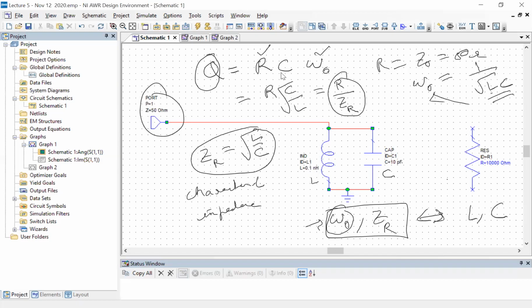To make a very large capacitor at microwave frequencies is very hard. Even 10 picofarads, as written here, is quite hard. You can of course design one, but it will not behave like a simple capacitance. It will have other associated properties which will make it look not like a capacitance.